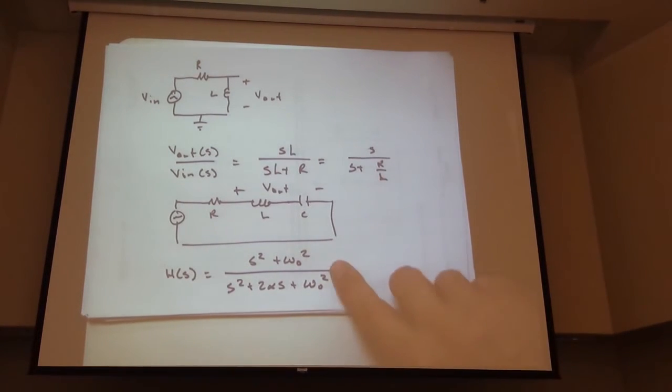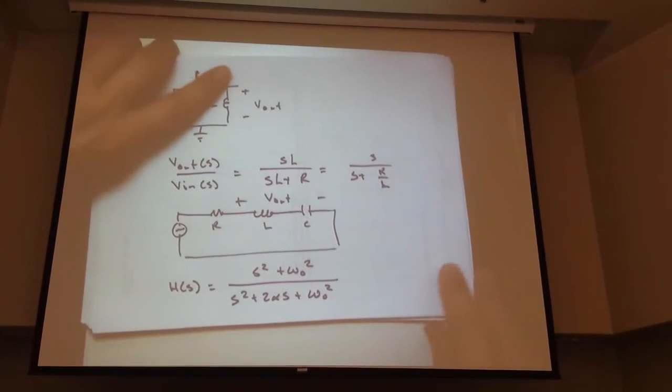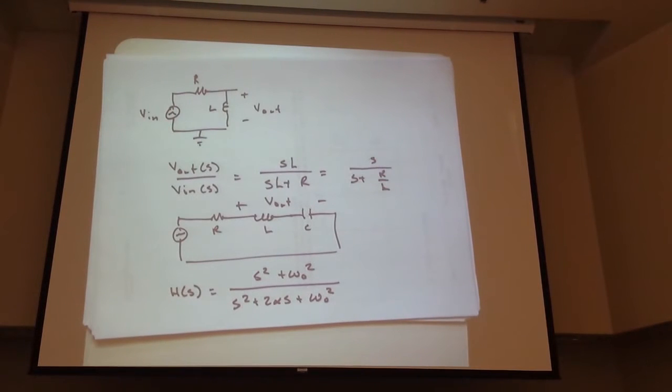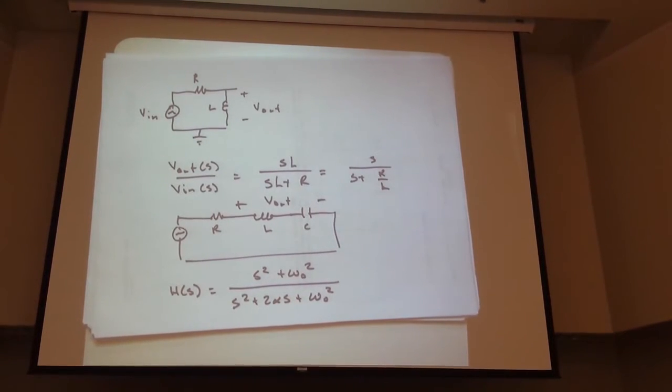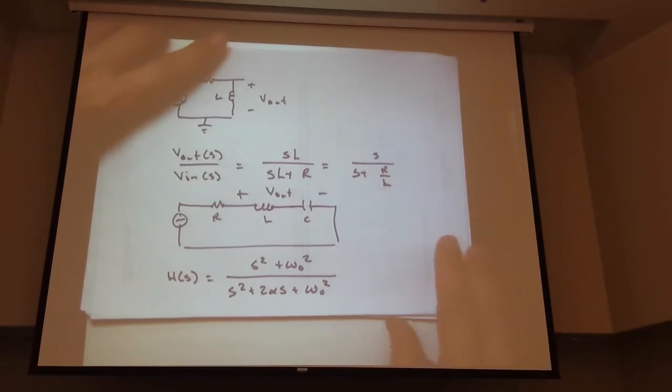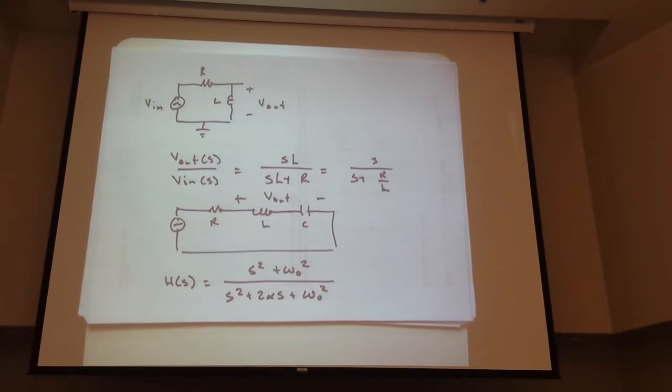Now, that's not saying you can't have more complicated circuits where you can design for the zeros. And you do. So it's not out of the question, but in our simple circuits, they're an artifact. But you would never design for a 0 at 0. It's not a circuit design, it's an artifact of where you're measuring. In this case, you design for the poles and the 0 falls out somewhat automatically, even though the 0 is meaningful.